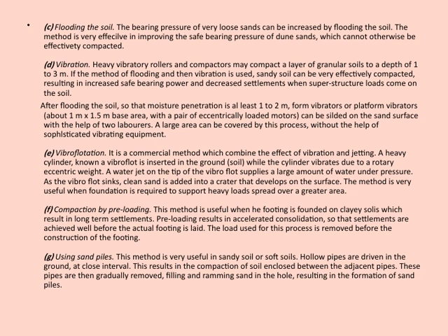Another technique is compaction by preloading. This is especially beneficial when dealing with clay soils that tend to settle over time. Preloading involves applying a temporary load to accelerate consolidation, causing settlements to occur well before the actual construction begins. Once the settlements are achieved, the load is removed, and construction can proceed on a more stable foundation.